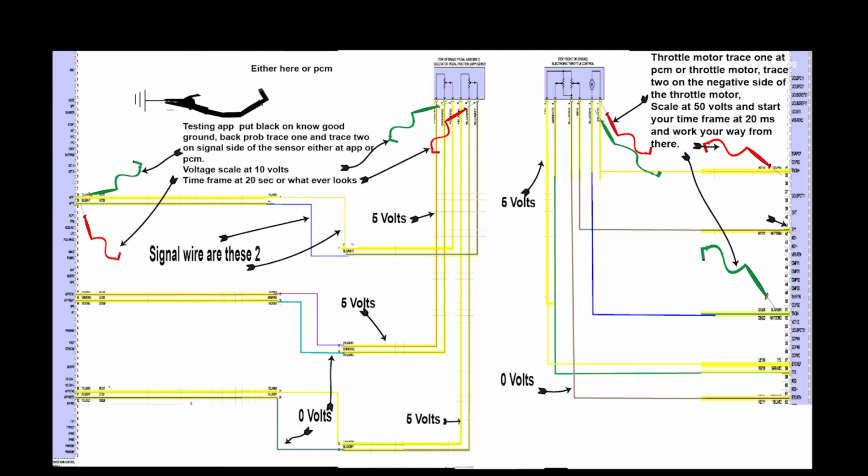Hey everybody. This page here is to show how you can back probe to either get your voltage sensors or to check your scope pattern and where to go to check your scope.